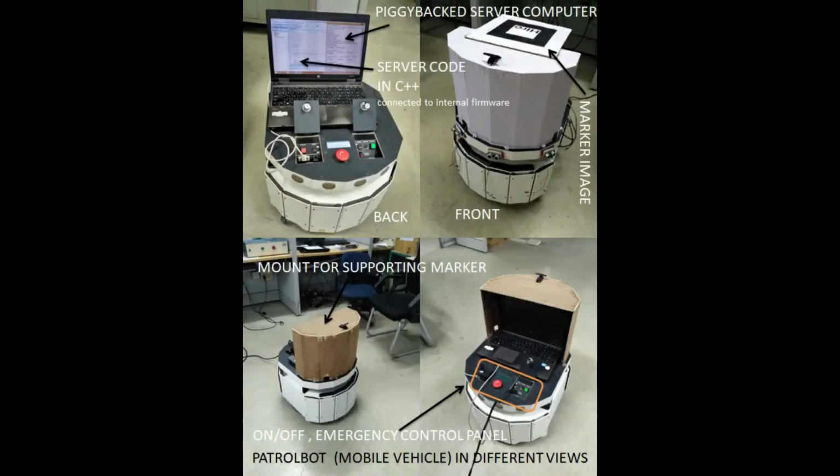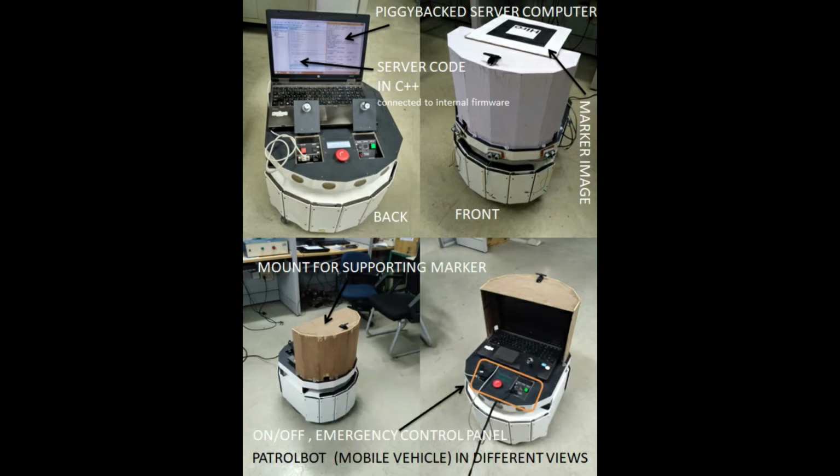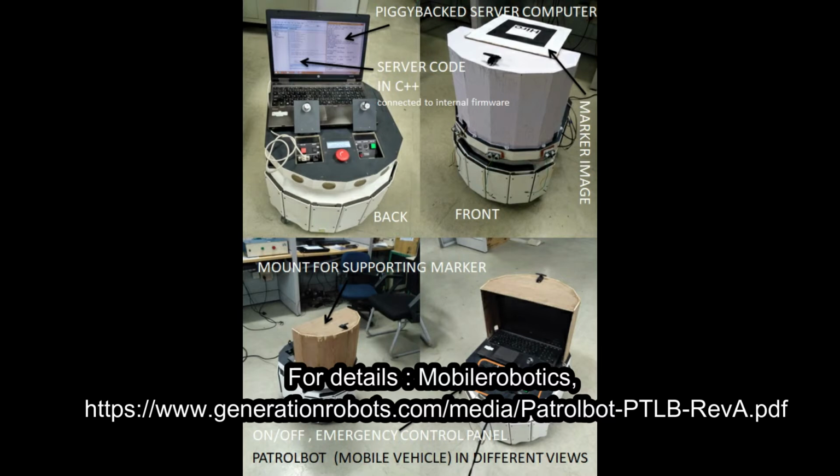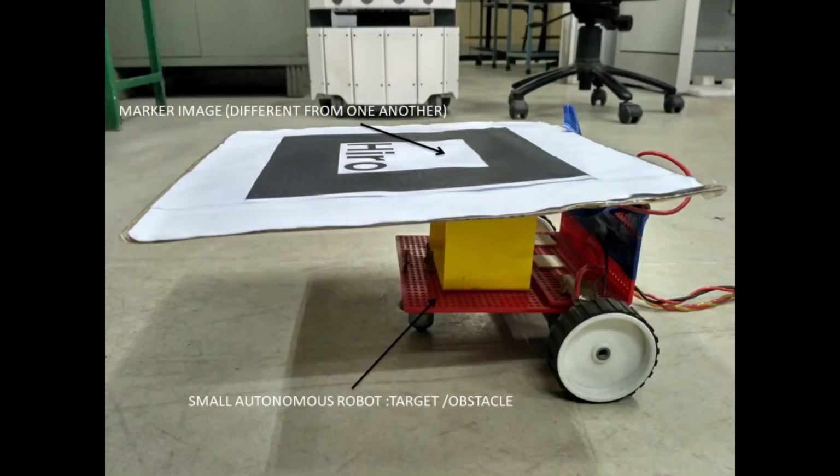The pursuer is implemented on PetrolBot, a research-based autonomous mobile robot by Adept Mobile Robots. It is a two-wheel differential drive system with a saturation velocity of 1.8 meter per second and a saturation turn rate of 300 degrees per second. The PetrolBot is configured to carry a piggybacked server that communicates serially with the internal firmware of the robot. The robot is configured to accommodate image-based markers, onboard cameras, ultrasonic sensors, inertial measurement units for supporting various navigation-related experiments. The target and the obstacle are configured as small autonomous robots which can execute a commanded trajectory.